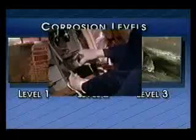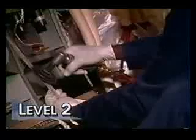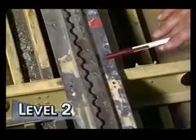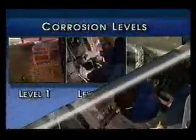Level 2 corrosion is more serious than Level 1 corrosion. Level 2 corrosion is defined as corrosion occurring between successive inspections that requires rework or blend-out that exceeds manufacturer's limits. Level 2 corrosion can also be widespread, extending beyond one bay, which requires rework approaching manufacturer's limits. Level 3 corrosion is the most serious level of corrosion. If found during inspection, Level 3 corrosion requires expeditious action, since it affects the airworthiness and safety of the aircraft.